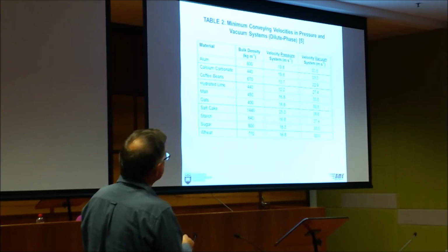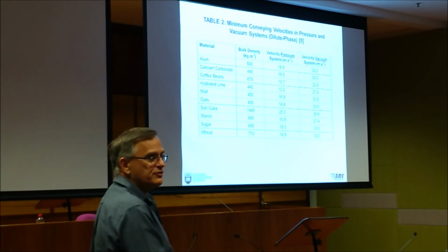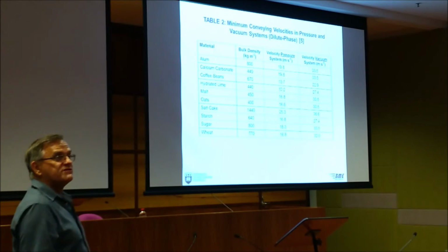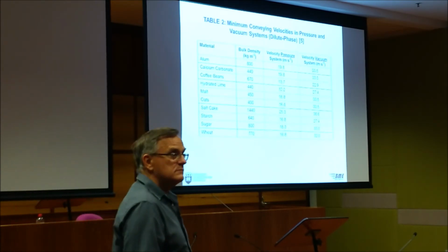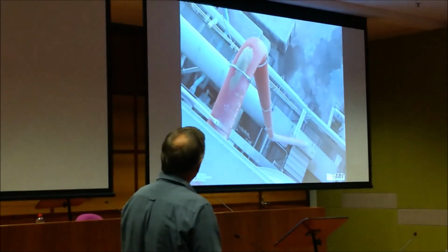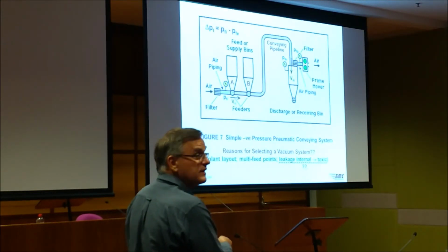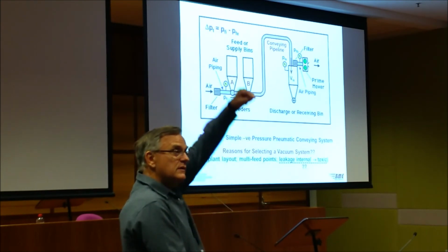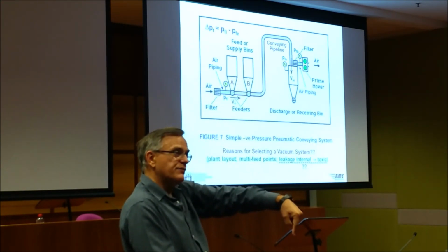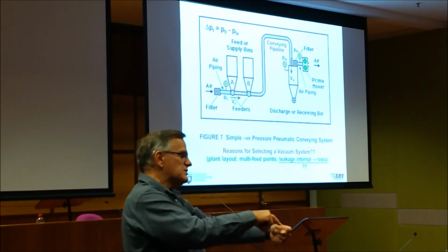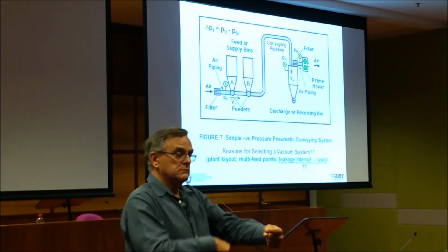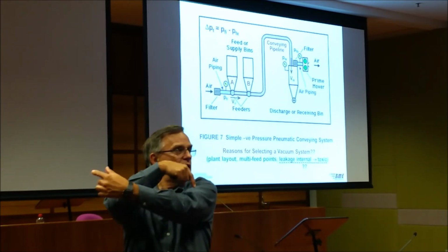But when we go to vacuum systems, the feed velocity is also higher than the positive pressure system. Why? Again, the answer is physics. You have to understand a couple of basic things. This is a vacuum system, right? When we drop particles down there at 10 tonnes per hour, we've got a certain momentum of particles going that way, and to pick up those particles we need a certain momentum of air. Right? Momentum balance to get the thing going.